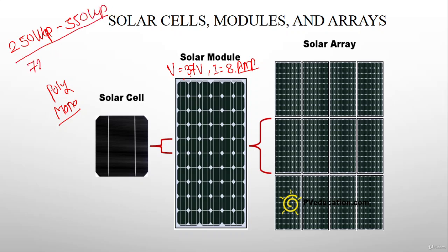In this case, we are going to use 72 solar cells with 12 cells in each row, so 6 rows are possible. Whenever we join solar modules in series combination, it becomes one string of solar modules. In solar home systems of smaller capacity, we can decide how to connect the panels in series or parallel combination as per the charge controller rating and the overall battery system voltage we are considering. That parameter will be discussed in subsequent case studies in this course.